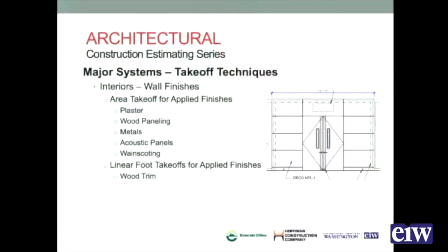Those are all taken off per area. Things that you would look at on a lineal footage basis are things like wood trim, little trim pieces, chair rails, and trim around a door opening. Those are things that you'll take off on a lineal footage basis.